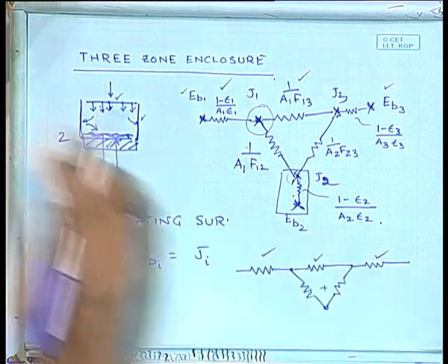So, a radiating surface is very common in many engineering applications where you would like to have the outside walls of the furnace as close to insulated as you can. So, in certain cases you can assume that one surface is perfectly insulated, you do not add or extract any heat to the surface.